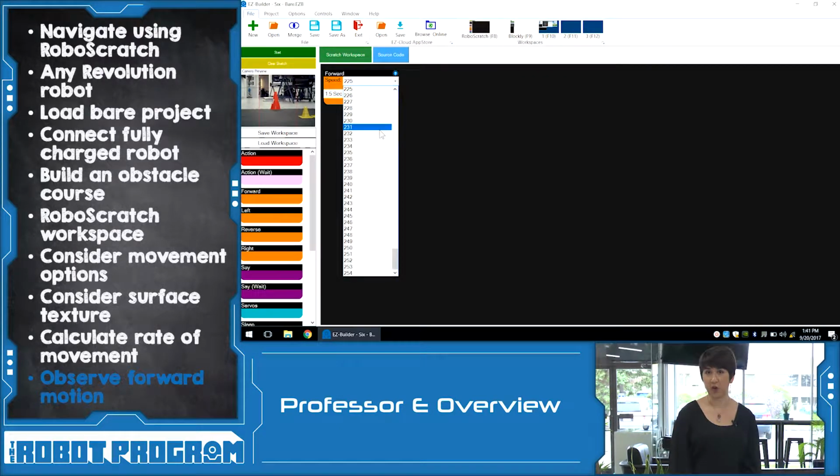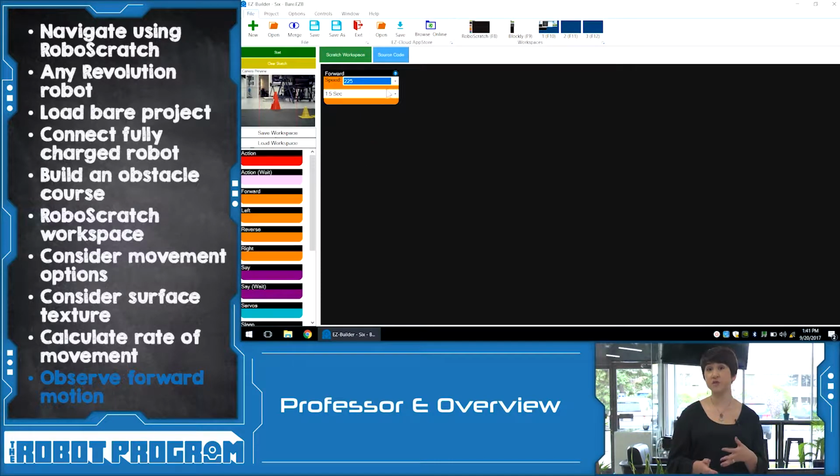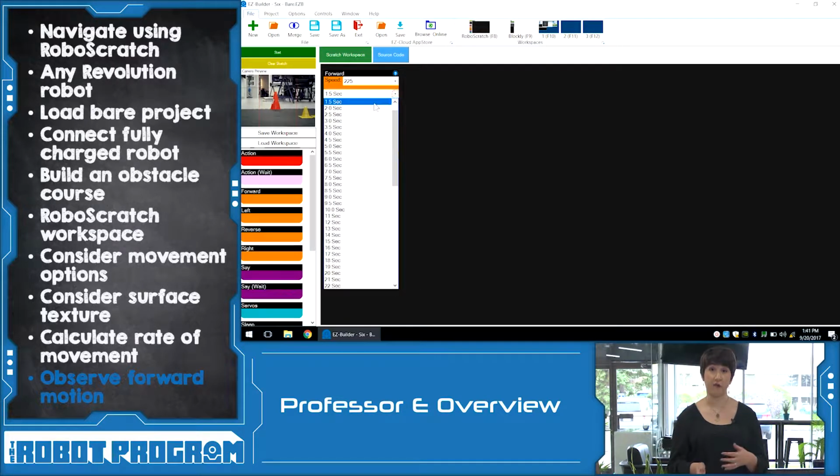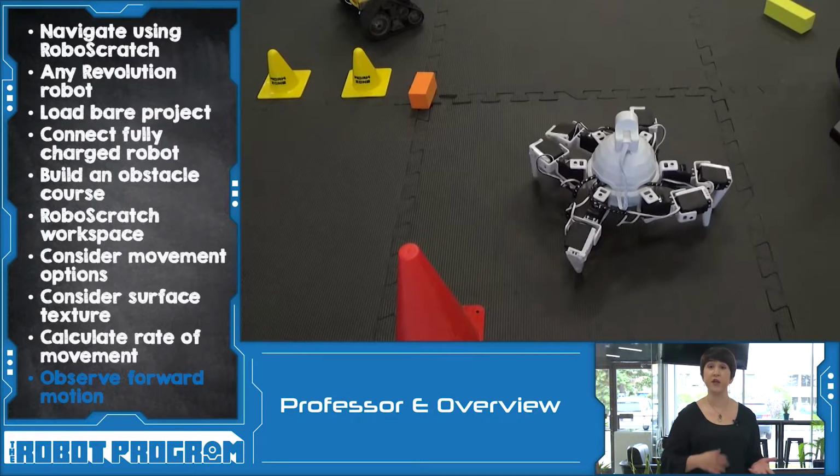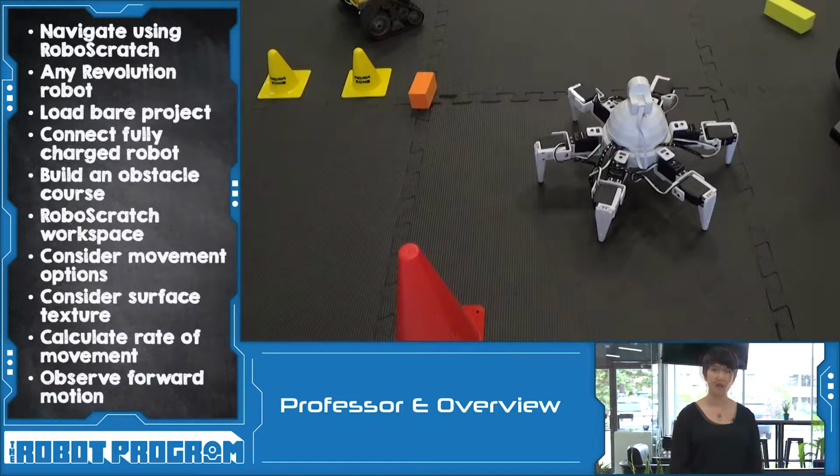Add a forward movement block and choose a speed depending on how fast you want your robot to go. I wanted the robot to take the obstacle course at a fairly quick speed, so I chose a speed for 6 around 225, almost near the maximum speed. Once you've chosen your speed, see how far your robot can move in 1 or 2 seconds. This way, if you need your robot to move a really long distance, you'll know if you need 10 seconds or 15 seconds. You'll be able to make a more educated estimate.